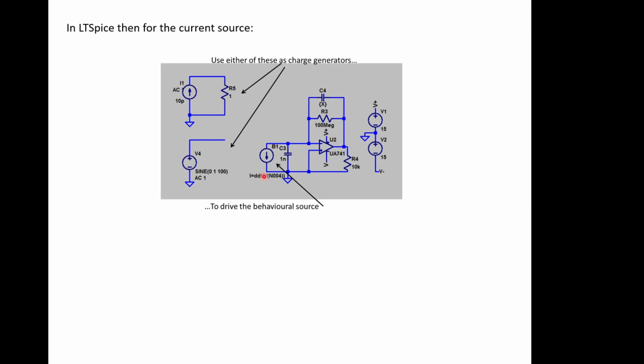So we can put whatever function we like in this box. In this case we've said, let's call it d by dt of some other voltage. So if we say it's this voltage here, we're then doing the d by dt of that, and that gives us our s term. So we are now simulating a charge source directly in here by generating a voltage here and differentiating it. So this is the use of a behavioural source where the behaviour is defined by other functions coming in. We could have typed just a function straight in this box if we wanted to. They're very powerful and very useful.